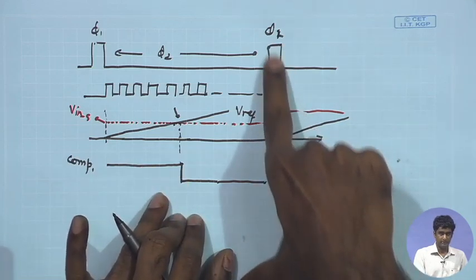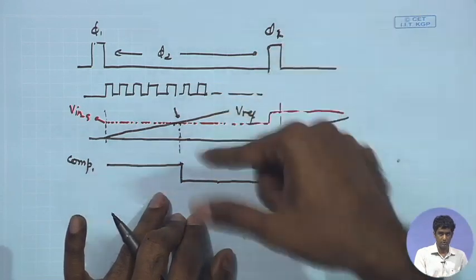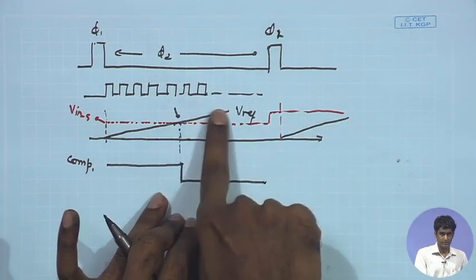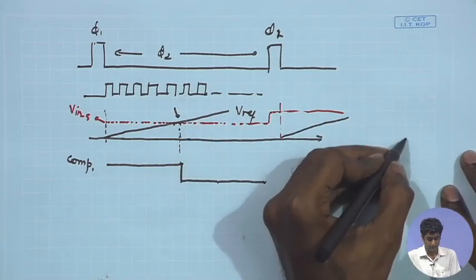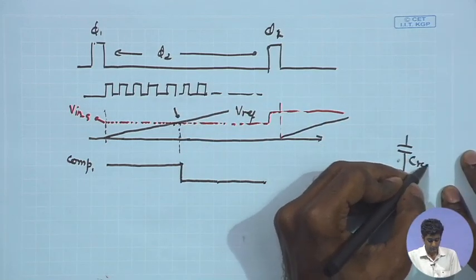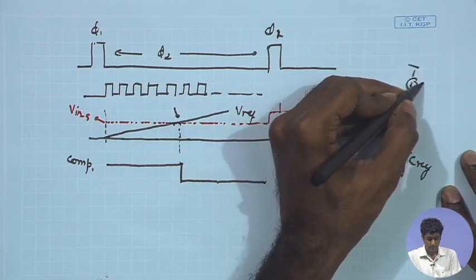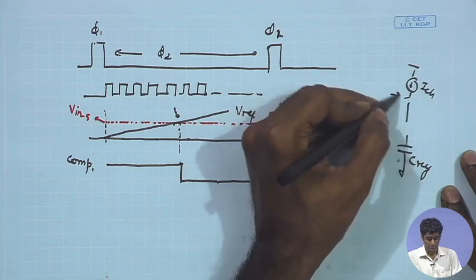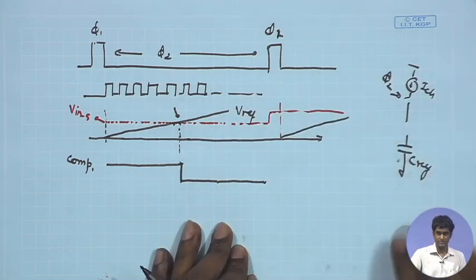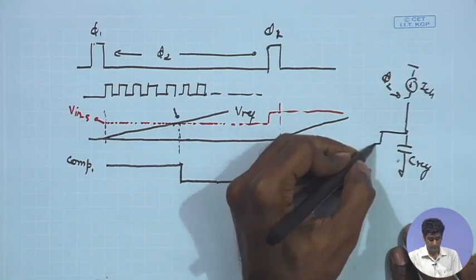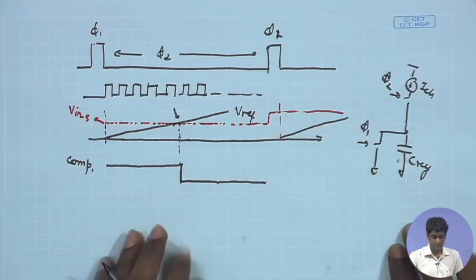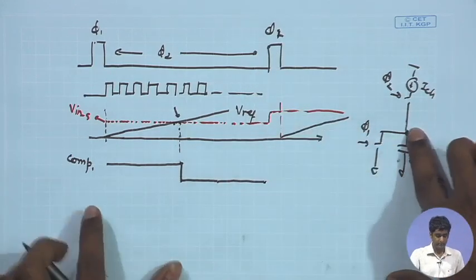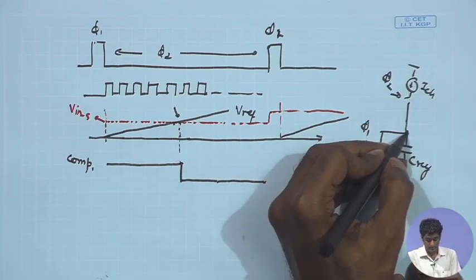We remember that we have a discharge switch also, which is shorting the C ref, which is basically storing the reference voltage. So, we have the reference C ref, and of course, you have the I charge that we have implemented using a current source, and you have the switch over here which is operated in phi 2 phase which charges this capacitor, and also whenever the phi 1 phase comes you have the other switch which is supposed to discharge this. So, whenever phi 1 is coming over here the VREF is again discharged to 0, and as a result